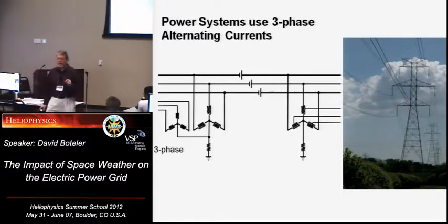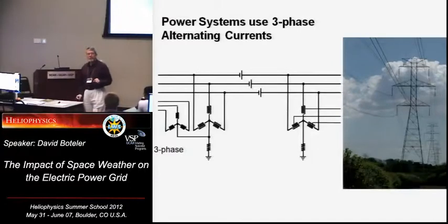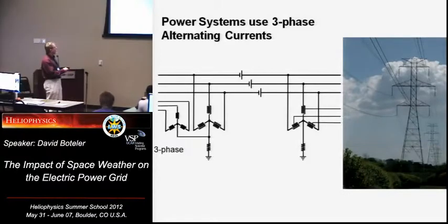Well, that is where one of the stability issues comes in with the power system. They're normally very careful about setting up the load on the three different phases to be all very equal. That's why down a street they do every third house, so averaged over the whole network, they'll be fairly even. What becomes a problem is if you've got very large industrial users, and if they were all on one phase only, like a car plant or something. But that's why they themselves go to three phase, and all their machines are operating on three phase. But yeah, that is an issue.